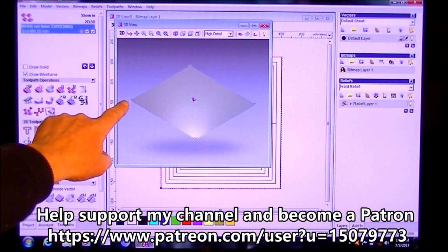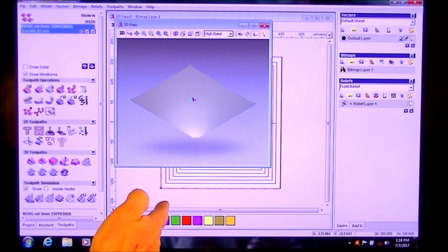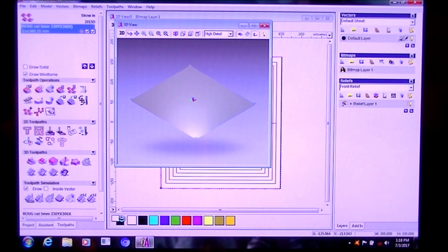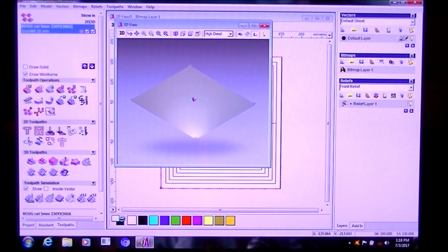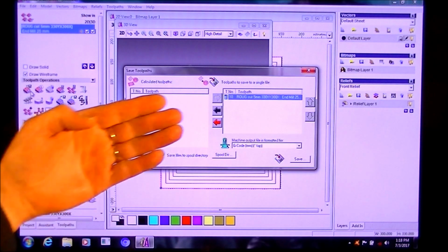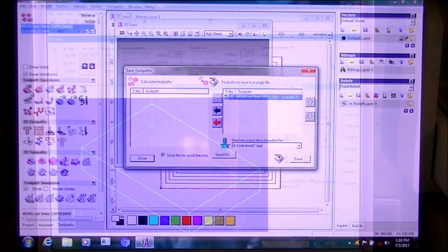And you notice there's little tiny corners showing as uncut, but in actual fact I have made the material size within the drawing about 15 millimeter larger than what it actually is. So these corners won't be left there, they will actually be cut away. So that's that. And then all you do is save that code to your flash drive and then put it into Mach 3.